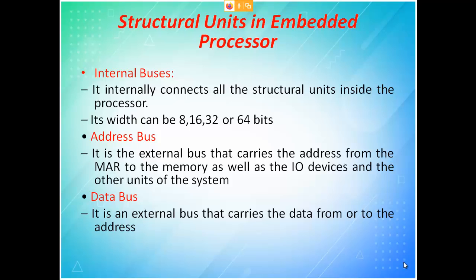If the data lines are also 16, the problem faced is that I developed the motherboard with 8085, where data lines are only 8-bit, and now if I introduce 8086, I have to throw away the entire motherboard, because the motherboard has only 8 data lines, whereas in 8086 they increased the data line capacity to 16-bit as well as the address also 16-bit.